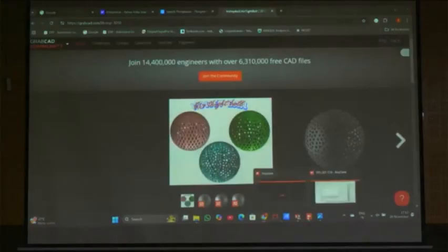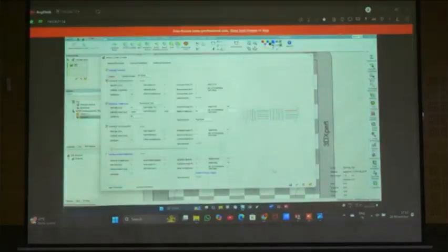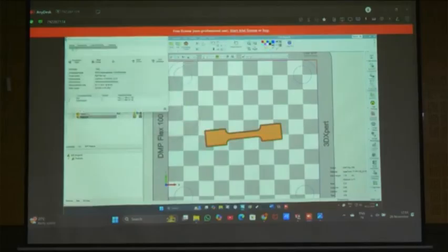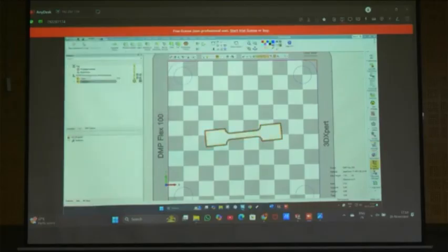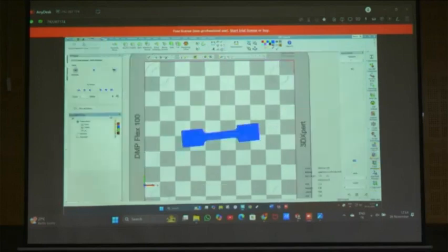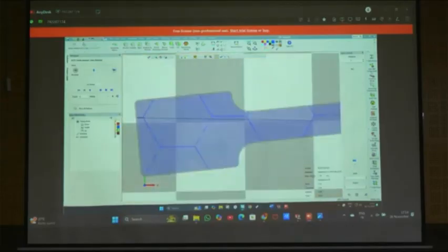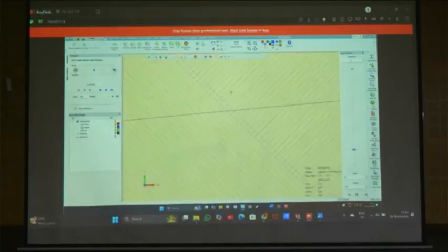So okay, we can go here. Once we fix the parameters, we can say okay, save and close. I think for the body we have changed the parameter to rectangular, alternated. This we can see in the slice viewer. See, here hexagonal shapes are there. Now again rectangular, now the part got started. Rectangular this is, and you can see alternated lines here.